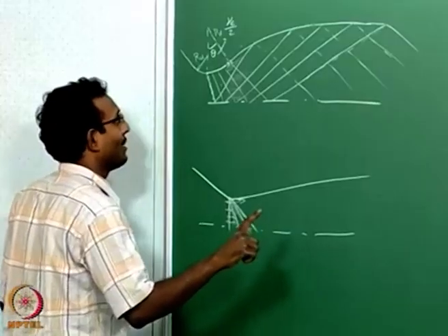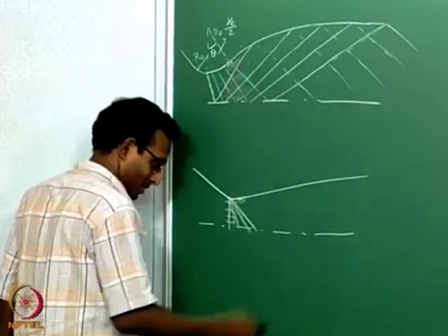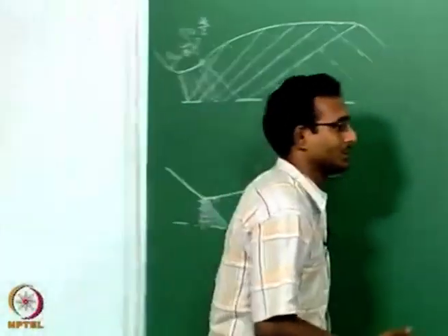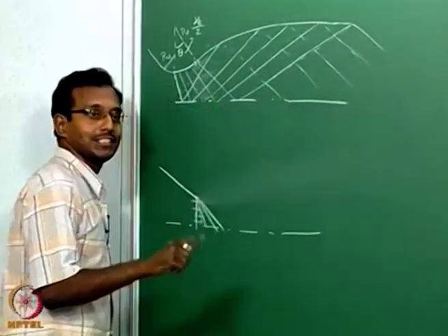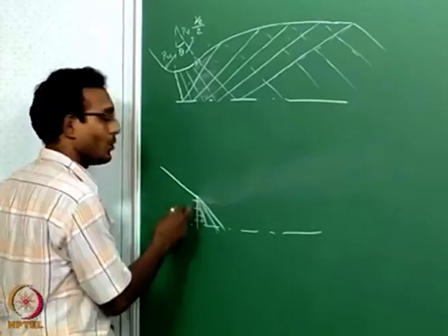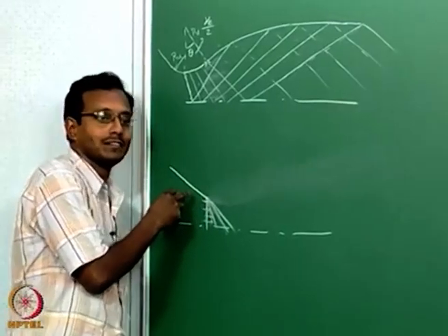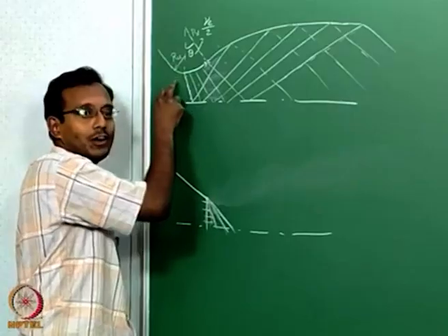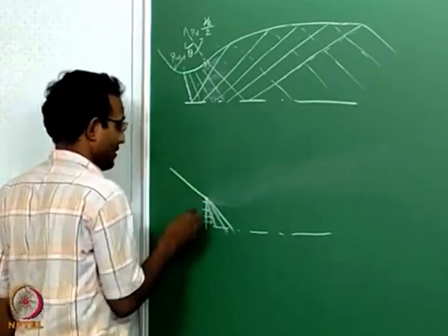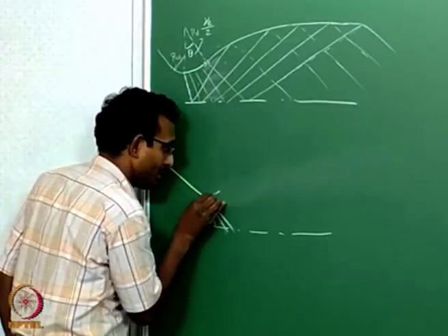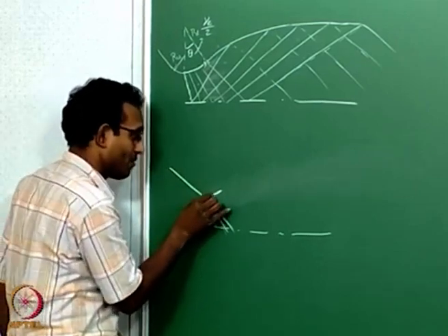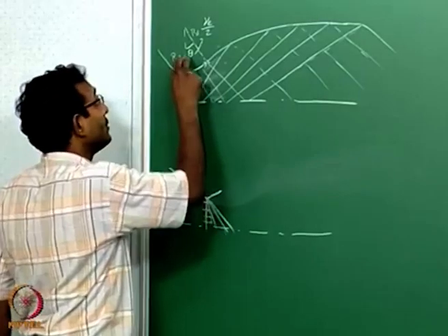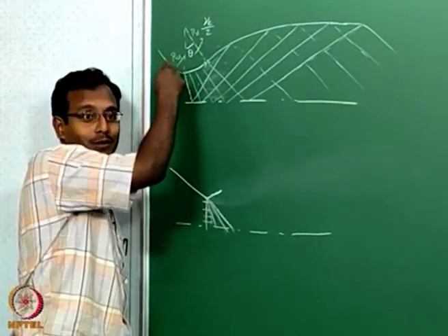Now one more detail I want to talk about in this nozzle design. If I had a situation where I do not have that upstream or the radius upstream here, so I cannot use my transonic solution, then I will assume my initial angle of my wall to be exactly equal to theta equal to nu exit by 2 as from the other calculations.